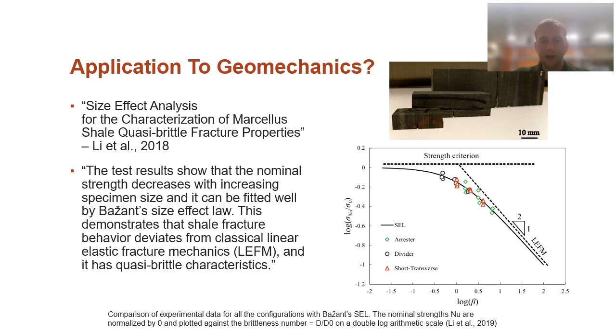Well, it actually makes a big difference, because when you think about test scale specimens, things like laboratory scale specimens are much smaller than what you would encounter in, say, the roof of an underground mine. So if you can properly scale your results according to this effect, you have a better idea of how your strength is going to change as you enter a real situation.